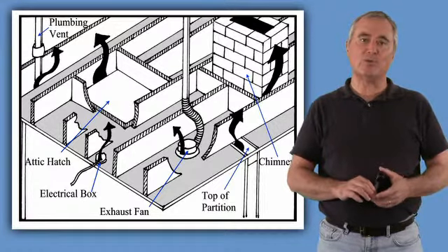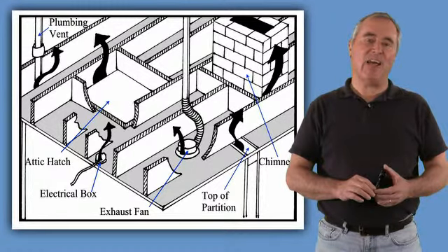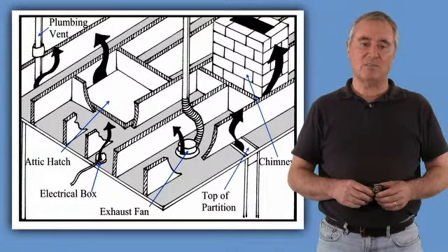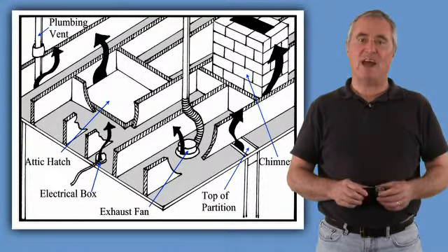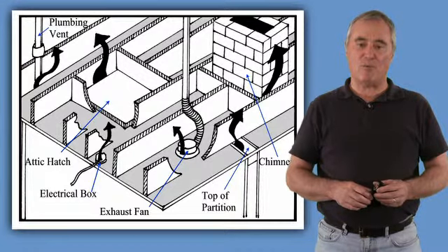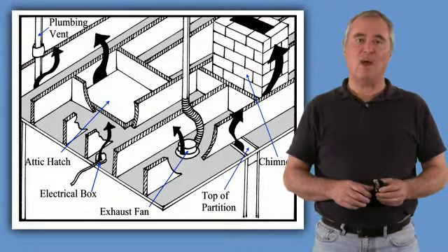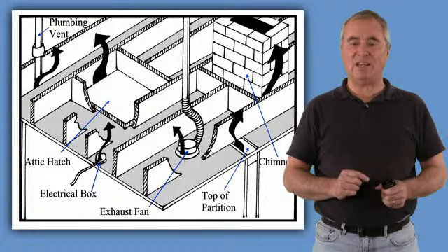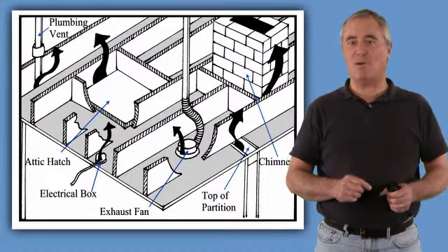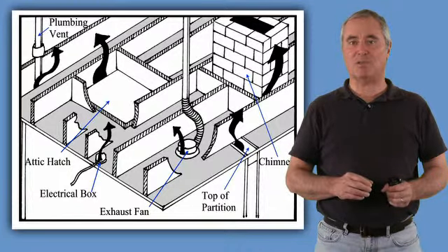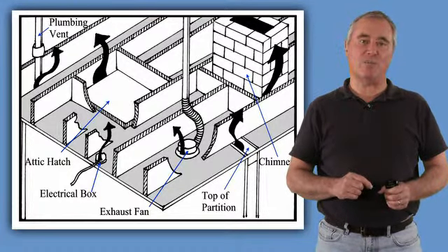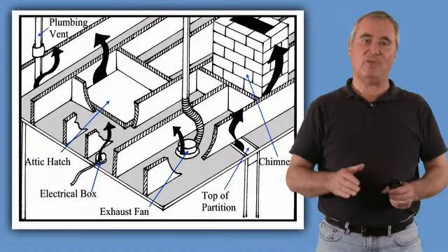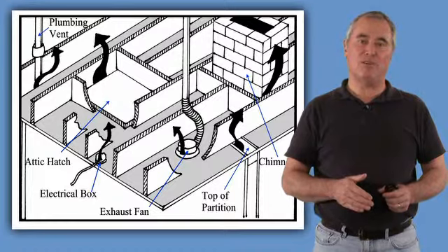So here it shows the typical places in an attic plane where we find leaks. Electrical boxes, plumbing penetrations, the attic access hatch, around a masonry chimney, around an exhaust fan, and the big diffuse leak is where the wall drywall doesn't seal airtight to the double top plates on the interior partition walls. So we're always sealing our ceiling drywall to the top plate 2x4.